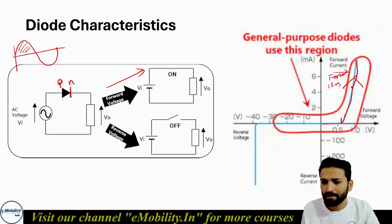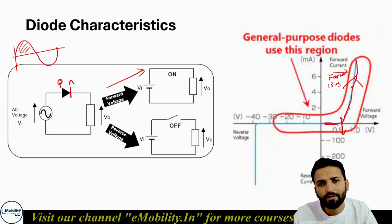For forward bias, the cut-in voltage is very important. As you can see here, at slightly more than 0.5 volt, the diode starts to conduct. Before that it was not conducting; the current was zero. Why was it zero? Because this is known as the cut-in voltage. This is the minimum forward voltage required to turn on the diode. For silicon, it is 0.7 volt. For germanium, it is slightly lower.